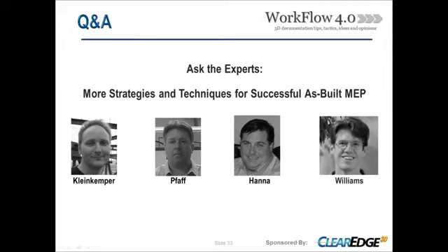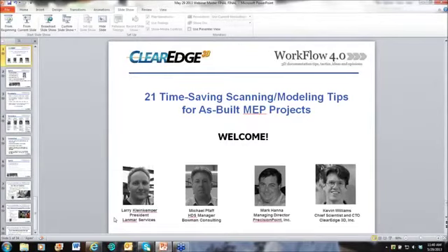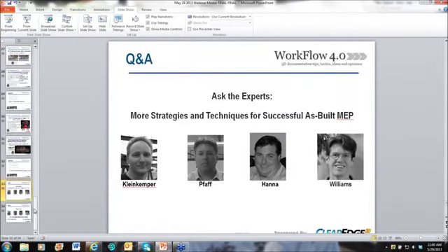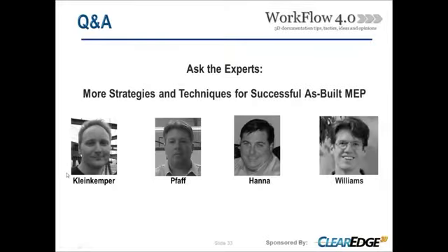A lot of times before we even get to a site, for sake of discussion, we might break a floor down, maybe in half, and we'll scan one half of the floor, and then we'll scan the other half of the floor as a separate cluster. We tie all that together with our survey control network, where we're locating some targets with the total station, and then we move up to the second floor, and so on and so forth.